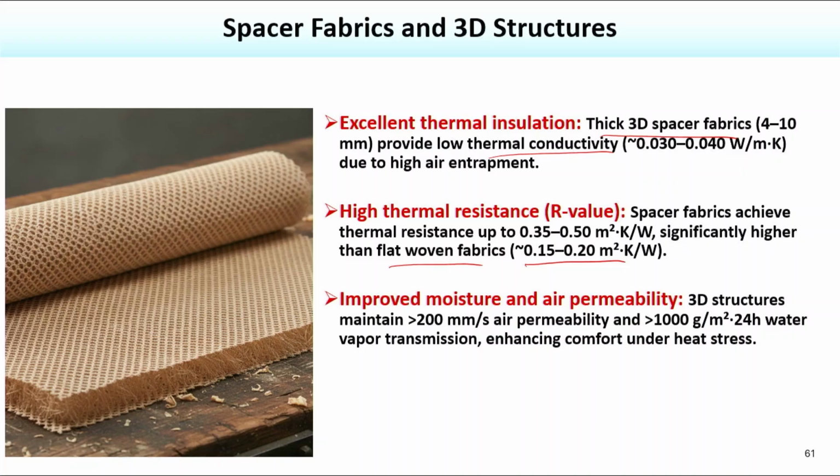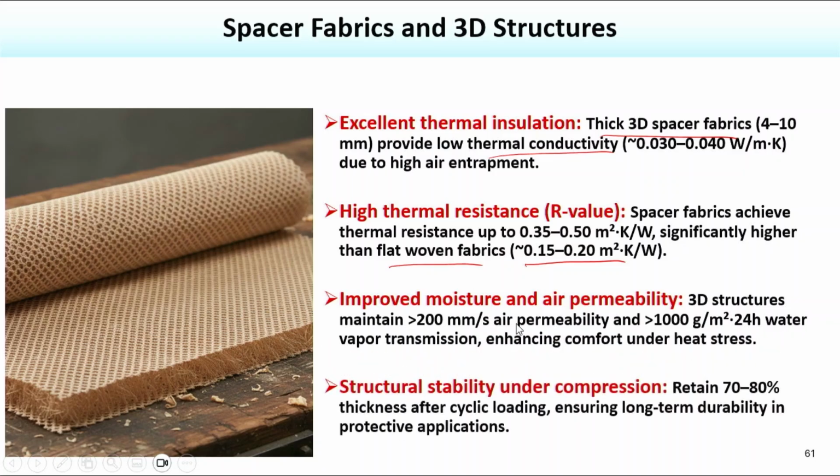And the moisture vapor transmission is very high, typically more than 1 liter per square meter in 24 hours, which enhances the comfort. So, we can achieve higher thermal resistance with improved air transmission and moisture vapor transmission. For those applications we can use the spacer fabric.